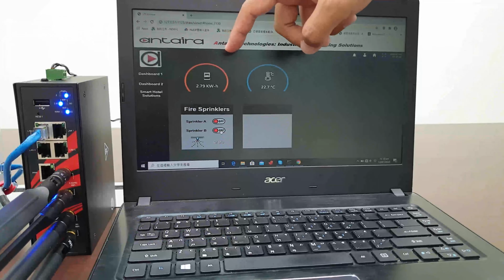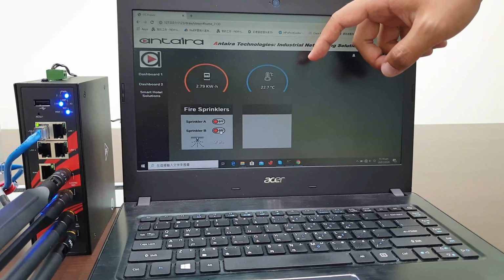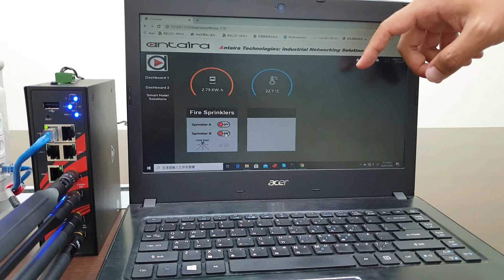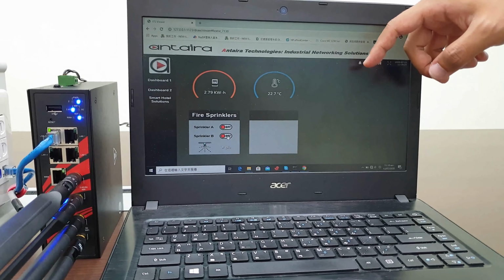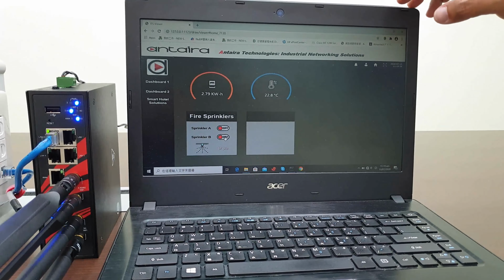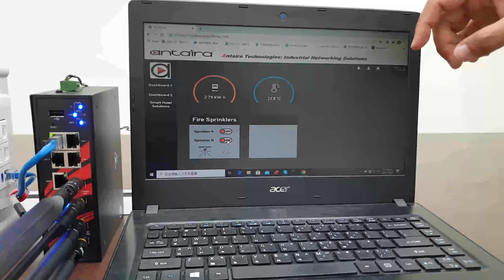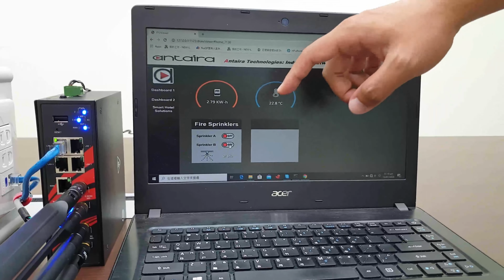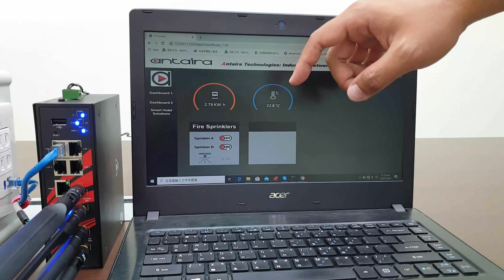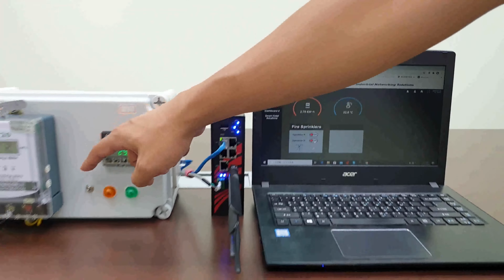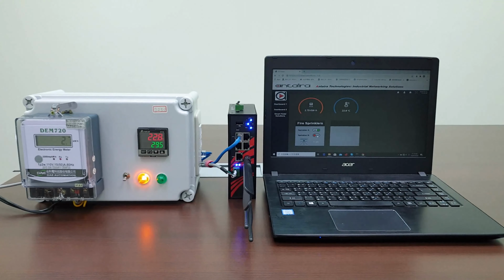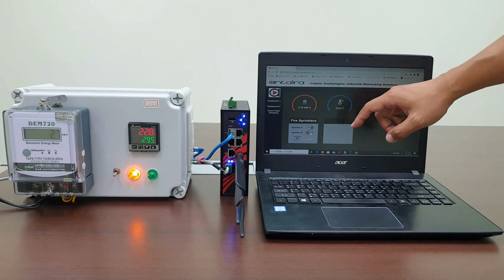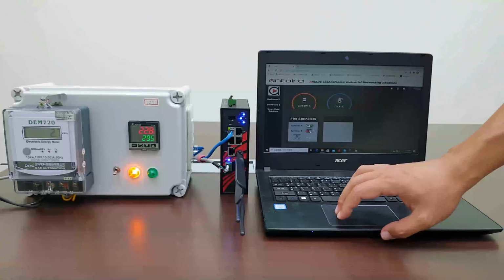The electric usage and the temperature can be used as a reference for reducing carbon emissions in order to improve the energy efficiency of a building. If there is a fire in a building and if the water pressure drops below the predetermined level, then the first pump will be activated. Lastly, the second pump can also be activated through the SCADA device.